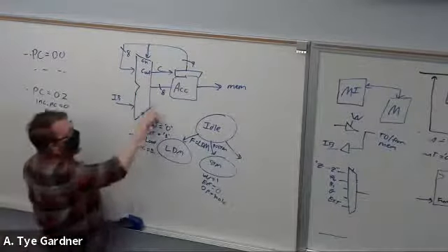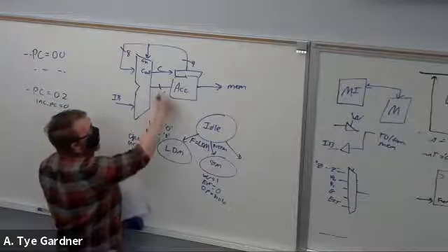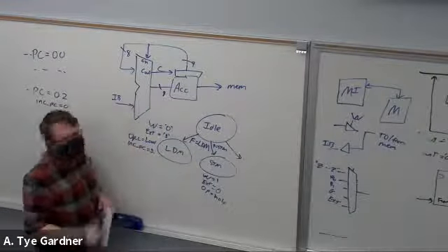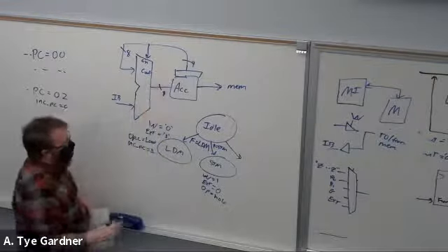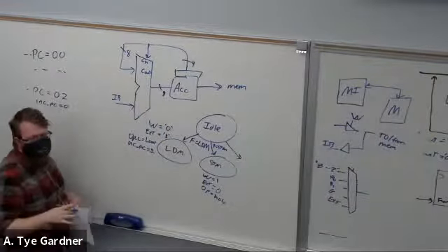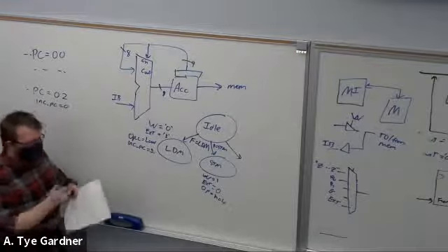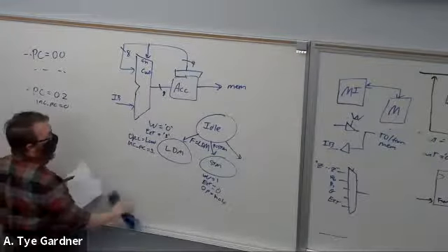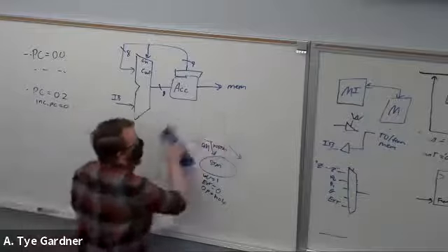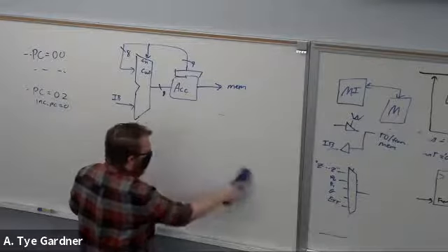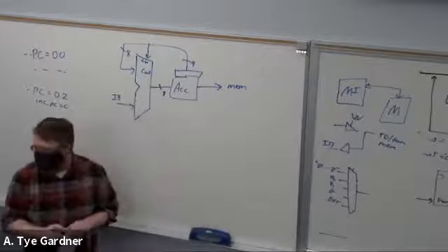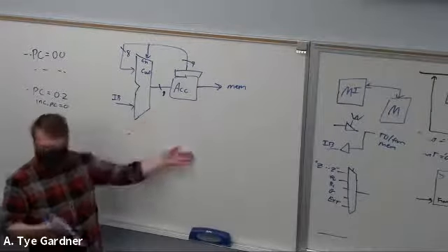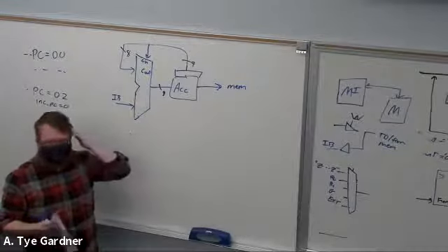Or you could just make this 9 bits and get rid of the C. Several of you did, there's a couple different ways to do this accumulator. Neither is wrong, and in fact, one of them requires more work, but I actually kind of like it. So one of them is to write the code for 9 D flip-flops, then use a generate statement to make 9 of them, and then you've made it.